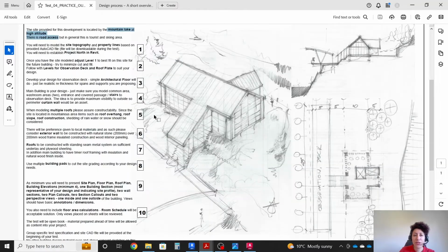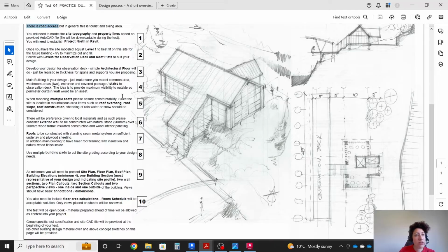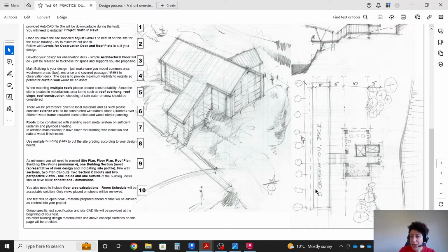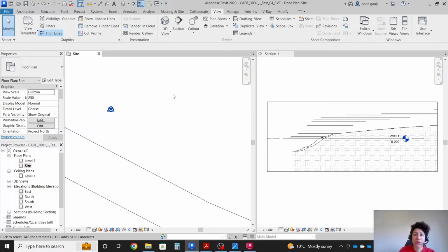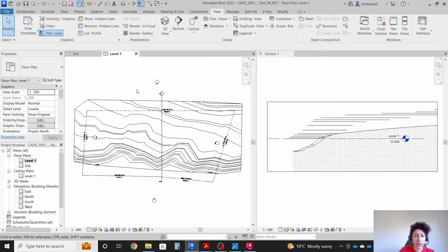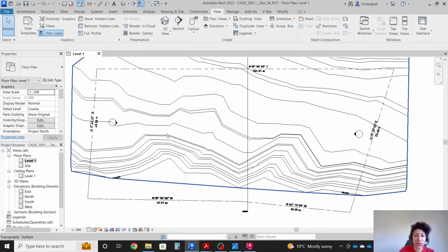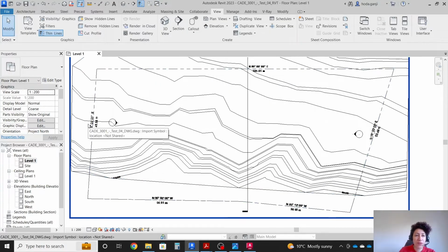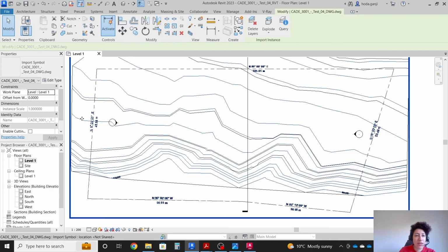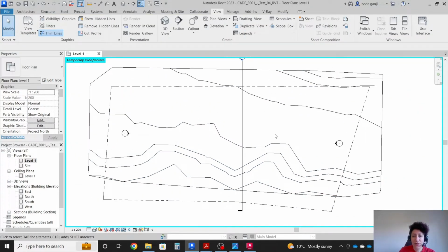I want to go back to our sketch. Let's say all our design is based on this nice sketch here. Now I'm gonna create maybe the spans here. How about I go and continuing from here where I want to set the grids, I want to go to level 1. I want to hit TW, and maybe I can close inactive views. Okay, we still have our DWG file here. I can click on it. In level 1, I can, for now, I'm going to just type HH and hide it. The rest of it is all our Revit stuff.